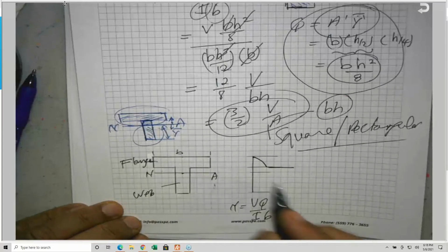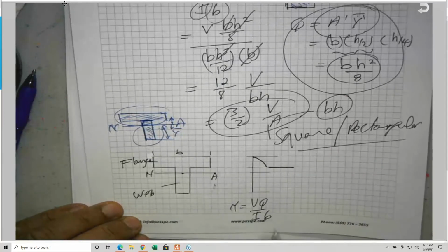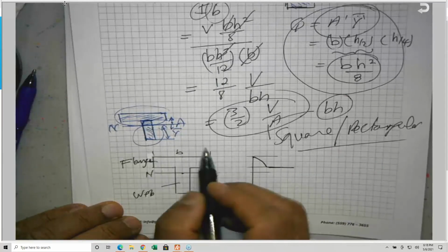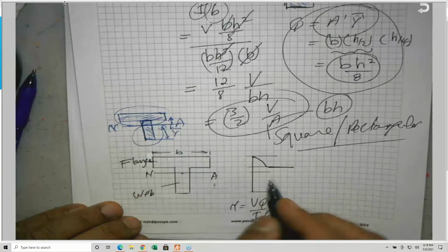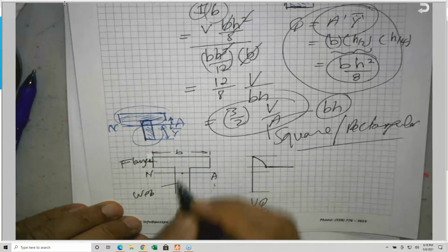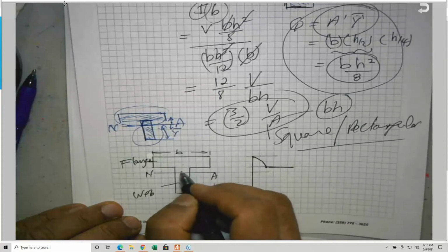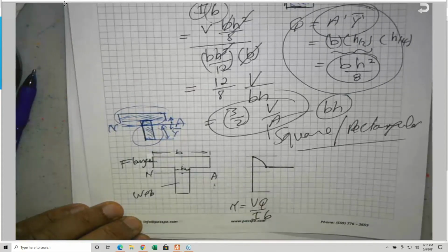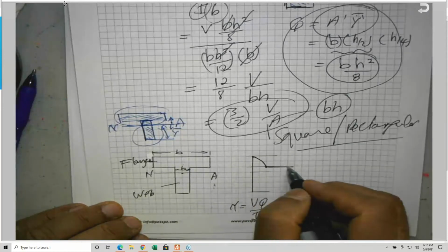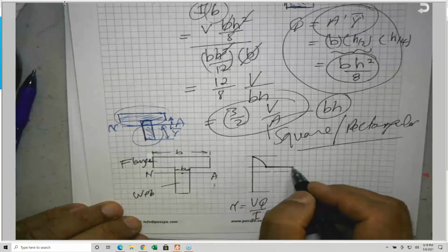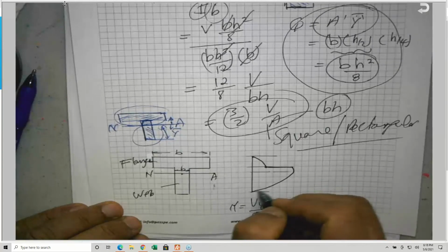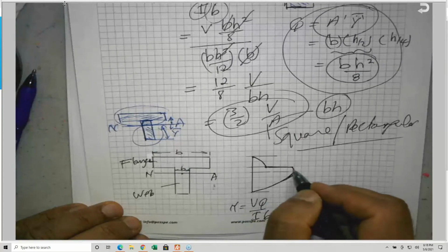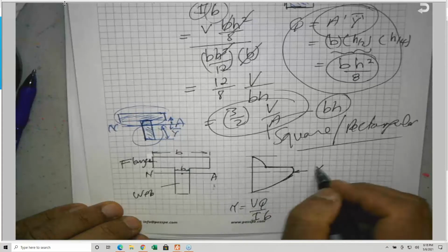So what B will be used? One time I'm dividing by a larger number, which is this one here. This will give me the shear stress here. The moment I transfer from here to here, I have a smaller B, which is the width of the web. So this is why the shear stress is jumping. And after that, it will increase to the maximum and start to come down. And here it is. This is tau max.